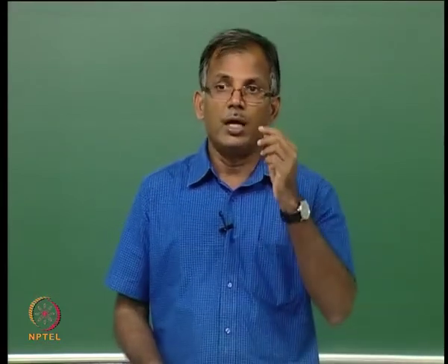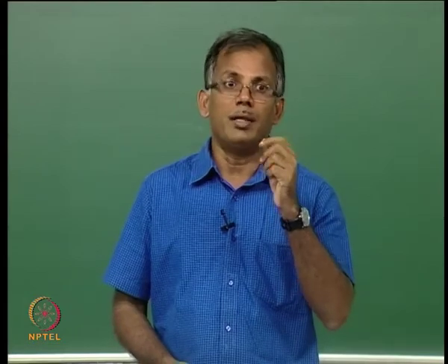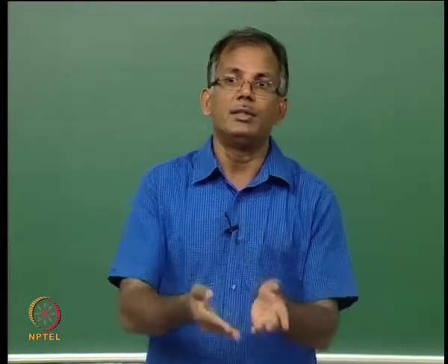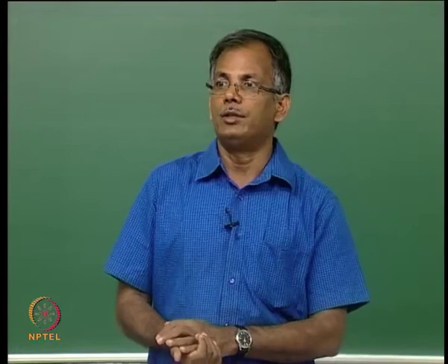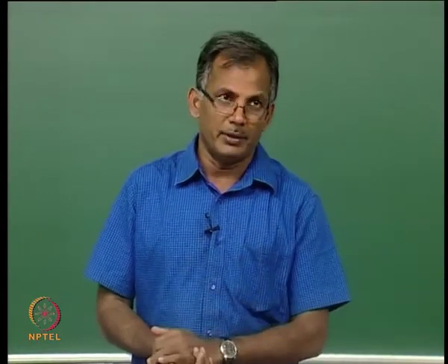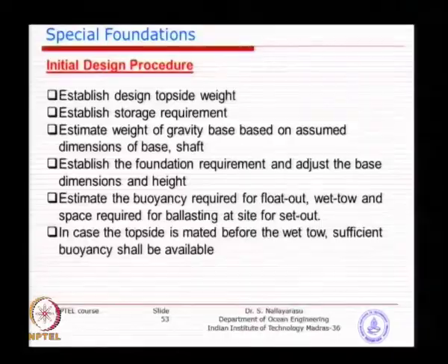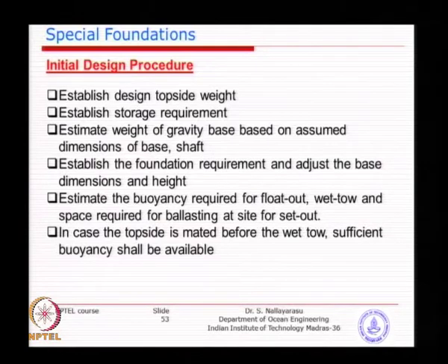Whereas we do allow negative pressure in the case of mud mats, because it is only temporary, in this case this is a permanent foundation, there is no other alternative. So you may not actually permit negative pressure. That means you have to make the foundation size large enough.